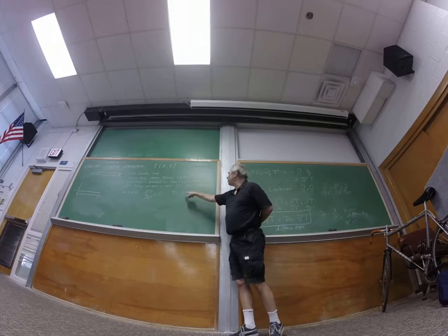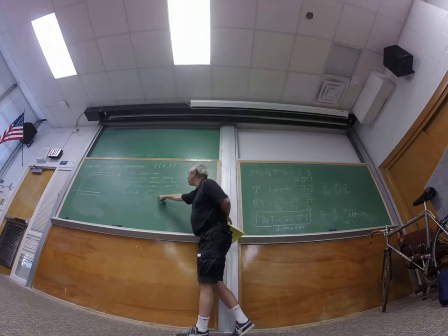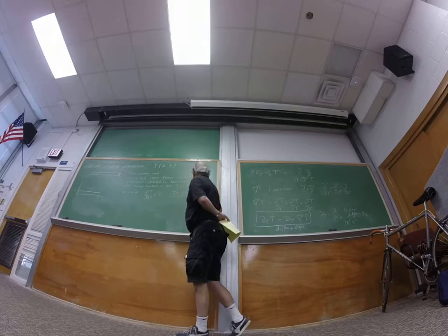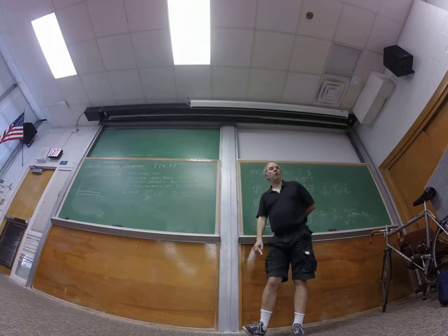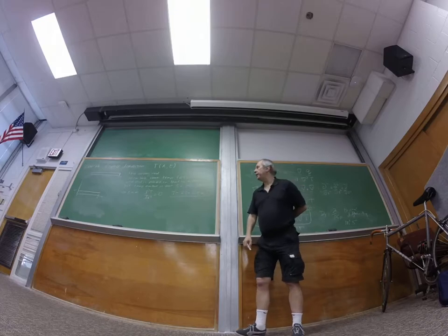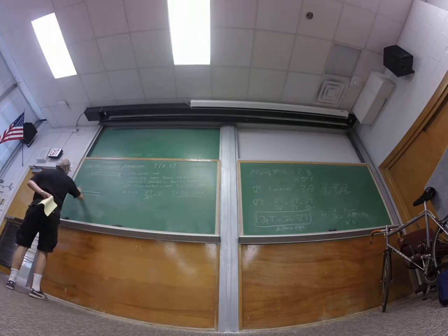So at x equals 0, it's 25 degrees. At x equals 30 centimeters, it's 25 plus 75 is 100. So I'm satisfying the boundary conditions at both ends. And we know, since it has to be a solution of this differential equation, that it can only vary linearly between the two ends. So that has to be what the temperature field looks like. Yeah, okay. So that's what happens at the end. So at the end, it would look like this.